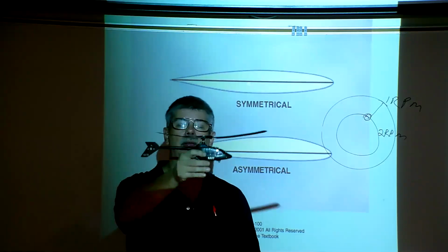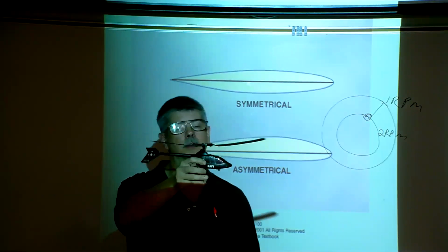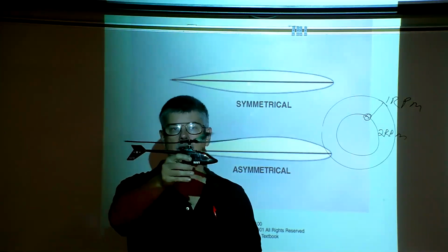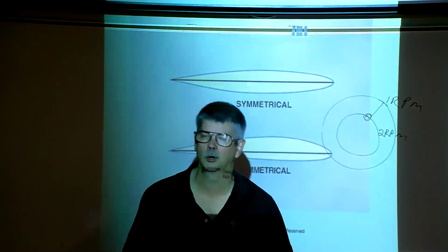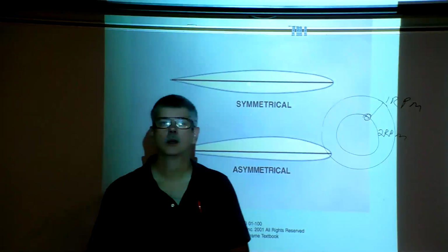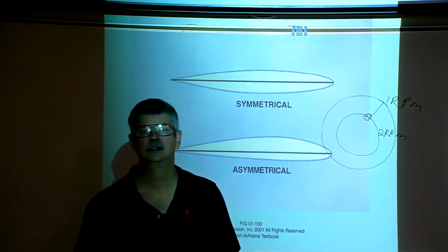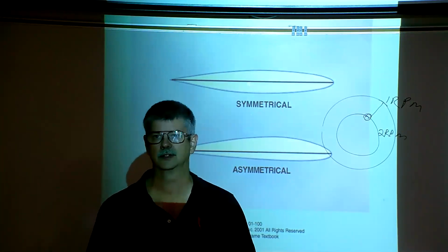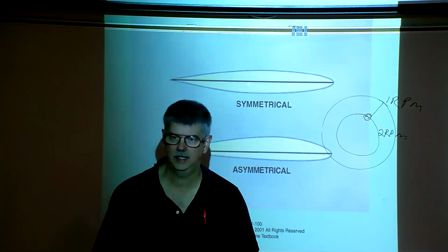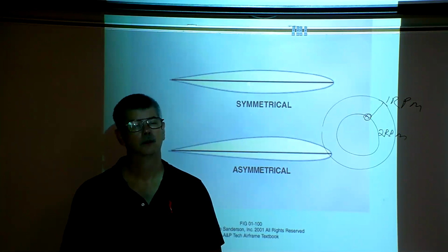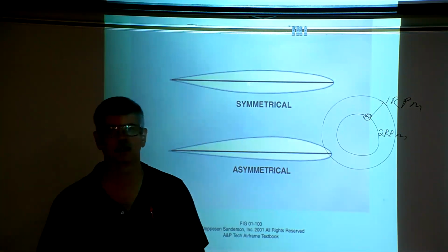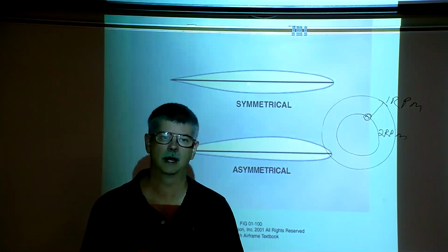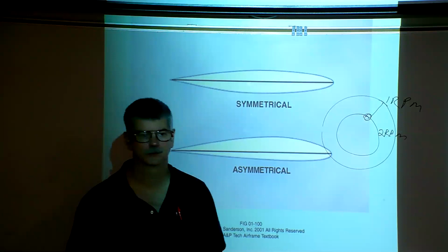Figure when the aircraft is out of ground effect, it's pushing air down. So we have what's known as a vertical component of that air. And this vertical component decreases the angle of attack that the rotor blades are hitting the air. Thus, with lift, remember, if the angle of attack decreases, the amount of lift is decreased.